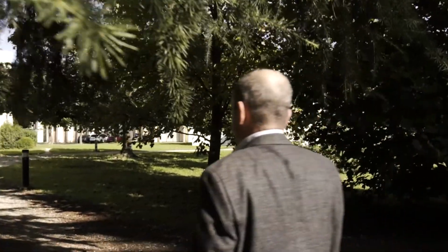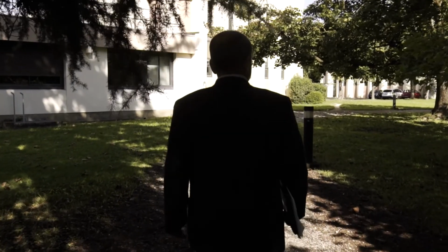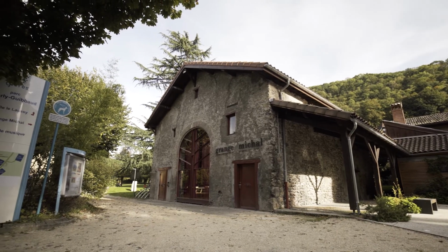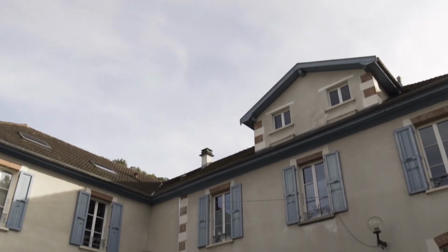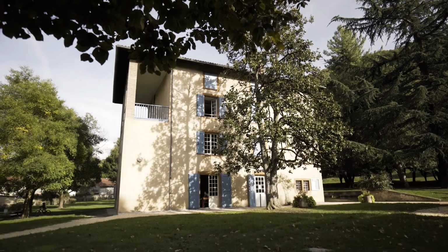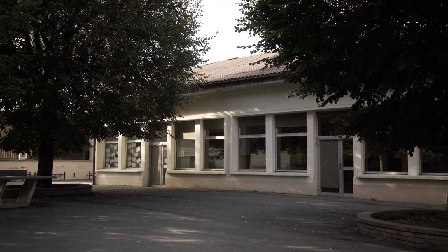As soon as renovation work is planned in a building, it is important to integrate the corrective action approach associated for its protection against radon ingress. Thus, at the end of the visit, the analysis of all this information makes it possible to assess the impact of the various characteristics of the building and its environment on the presence of radon, and to provide the necessary elements for the development of corrective actions adapted to the case under consideration and prioritized according to their potential effectiveness and the constraints of the project owner.